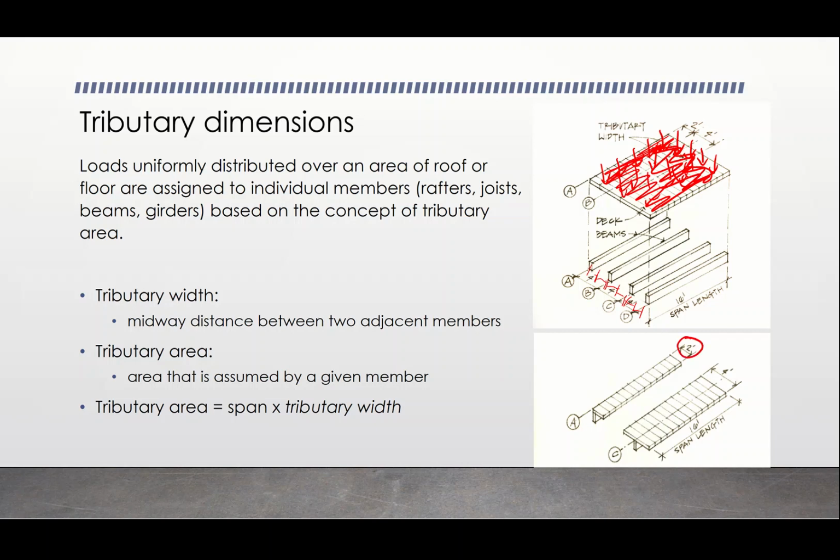So that is the little width that beam A is responsible for, 2 feet, and it is spanning over 6 feet, okay? So A is also 6 feet, but it only has 2. B, obviously, is more in the middle, doesn't have the side support, and so it has not only between A and B, but also B and C. So now that is B's, and so is that.